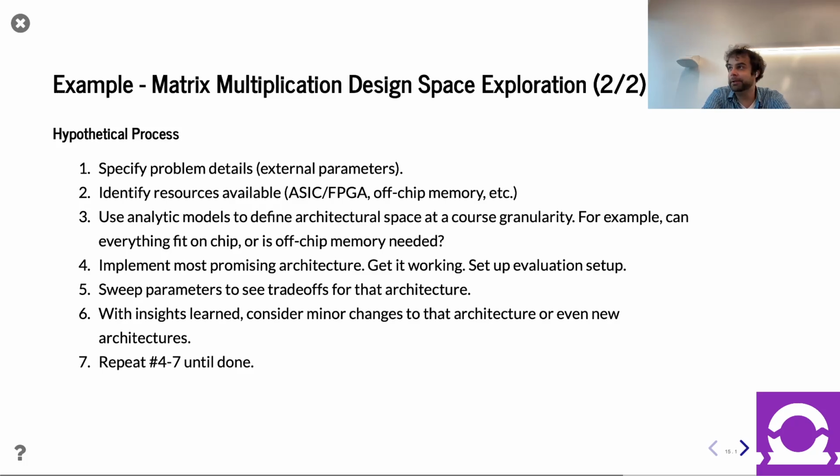Is what I'm hoping to build buildable, right? Am I trying to build a gigantic thing in an old process, 100 millimeters squared, and it's not going to fit? I should know that, right? That gets you a kind of sanity check on what you're doing. One way you might do this is looking at similar chips that have similar functionality and get a sense for what kind of resources they took to get that performance, and considering what your performance changes are, you can maybe approximate if you need more or less resources.